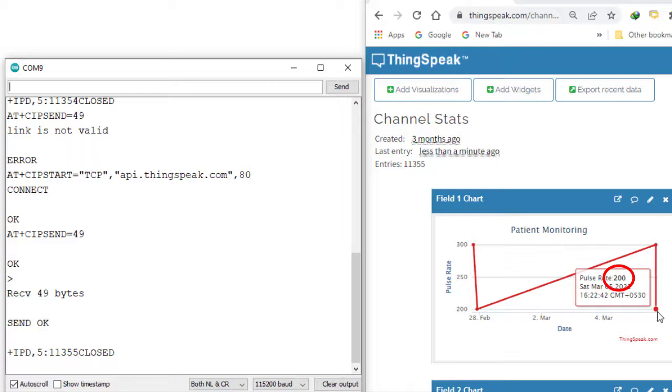So in this way, from ESP8266 we can update the data, or we can send the data to any server. Now I am showing what the type of response will be when we configure it as multi-channel configuration. For the case of multi-channel, the command is AT+CIPMUX=1.